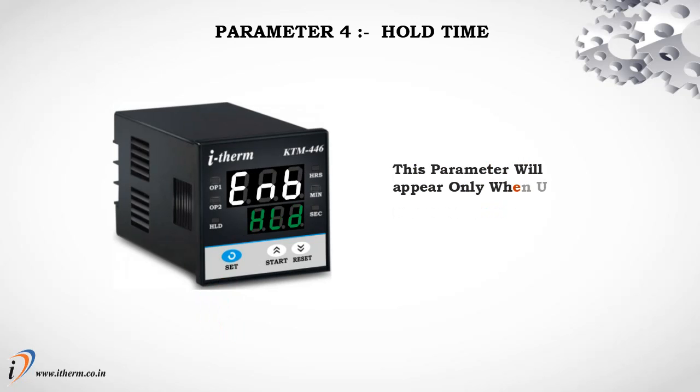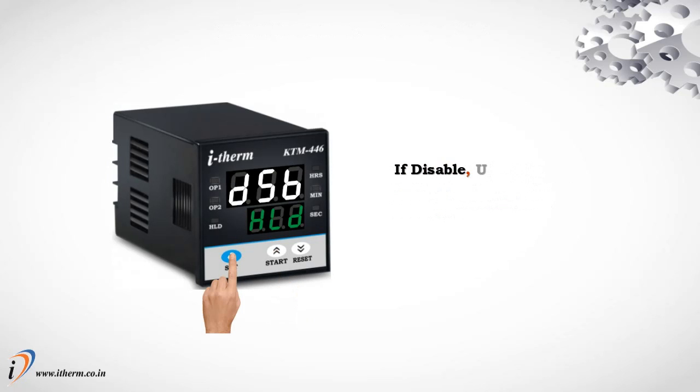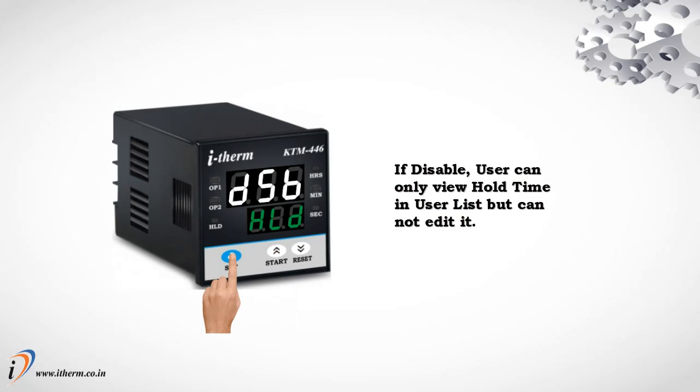Parameter 4. Hold time. This parameter will appear only when the user selects cycle 3 as the timer function. If enabled, the user can view and edit hold time in the user list. If disabled, the user can only view hold time in the user list but cannot edit it.